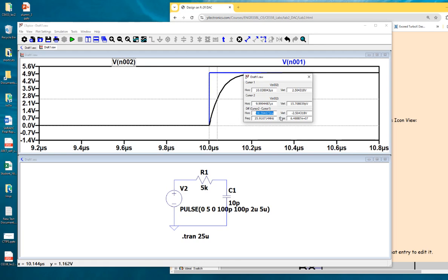So it should match. It wouldn't be exactly the same value, but it should be very close. Do a quick calculation. 7 times 5 is 35, adding all these zeros, so 35 versus 38 is very close. So it's probably 35 nanoseconds in theory in the calculation, but showing 38 nanoseconds in the simulation. So you can call it a match. The calculation matches your simulation.